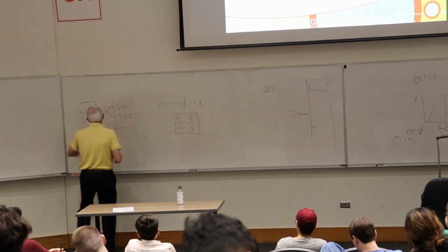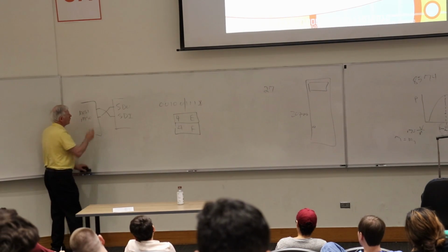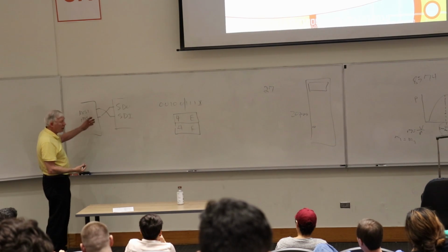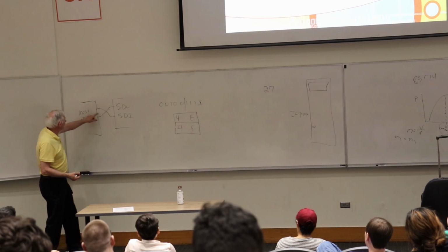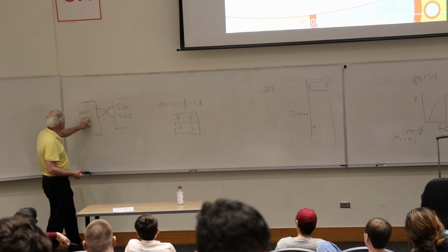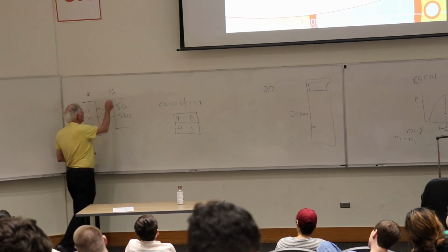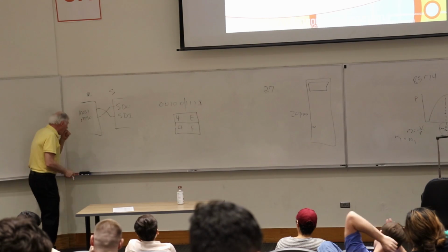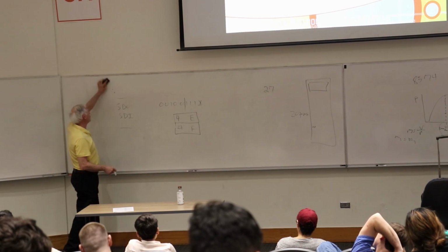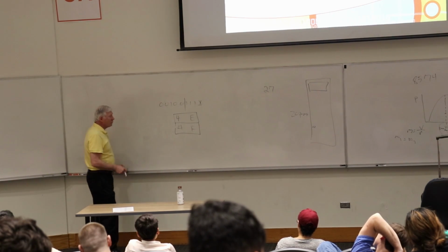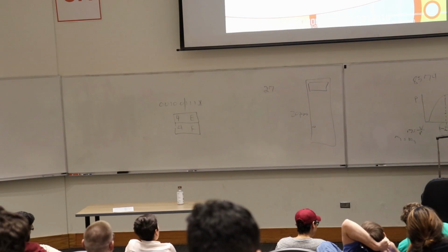And then what's really bad is if one's labeled MOSI and MISO, and the other's SDO and SDI, then you have to scratch your head and figure out what it is. Well, MOSI is master out, slave in, so that would be SDO. So that would go to the SDI. And MISO is master in, slave out, so that would be the serial data out from the slave. This is the master and that's the slave, so that would be crossed over again. So it's really nice if they use MISO and MOSI, but unfortunately, apparently, somebody copyrighted those, and so a lot of people don't use them because they don't want to get in trouble. It's irritating, but that's the way it is.